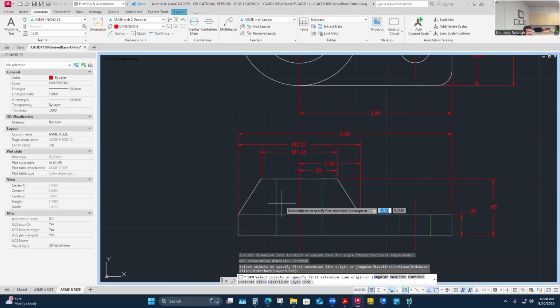Yeah, but what's kind of weird is that even though you're establishing the diameters here, you're not establishing them like a diameter from where, right? It's just this diameter of itself. It's a size diameter, but it's not a location diameter, right? So when I add these other two dimensions, they function more as a location dimension for those diameters.